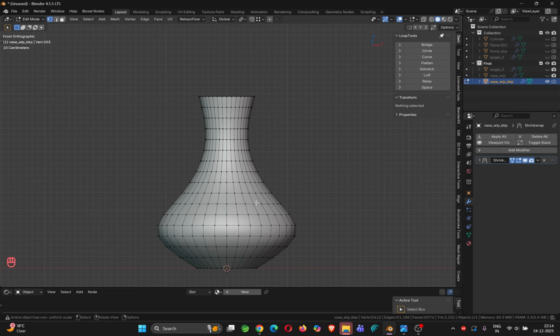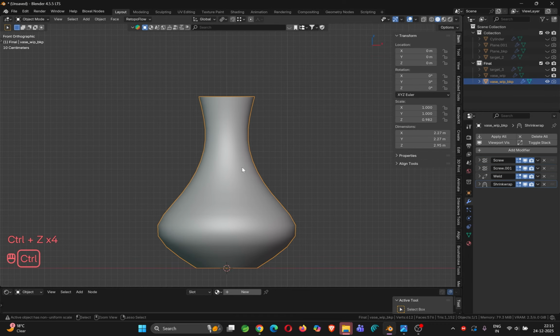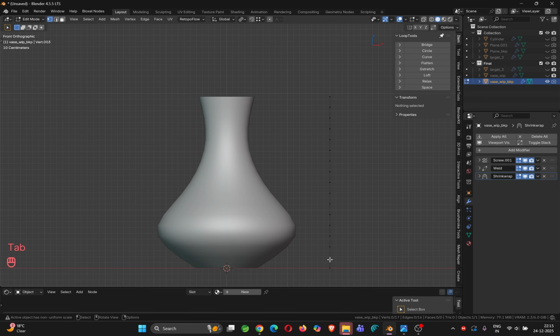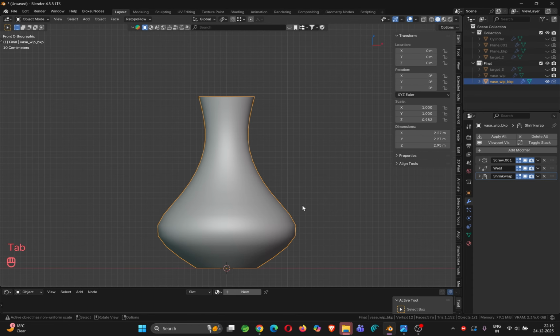and you can see that here this part is a bit squarish, but not here, it is long. Now tell me how you will do that change. So let's go a step back. Okay, what I will do, I will not fully commit the entire modifier stack here. I will apply this thing first and this thing first. What it will do, it will give me this vertex which is creating this thing.